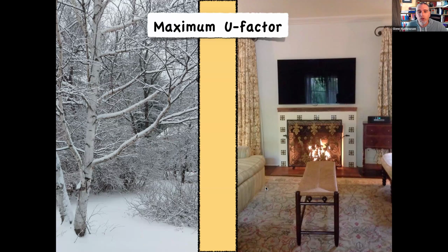With the U factor method, you calculate and determine the performance of your assembly by specifically what you built. So it's going to account for the studs in here. Studs have a pretty high U factor. They're going to allow movement of heat energy faster through the studs than, say, through insulation. So whether those are metal studs or wood studs, it's going to have a different U factor. This method lets you get credit, or counts you, for exactly what you're using. Metal studs or wood studs, 24-inch on center, 12-inch on center. How is your assembly built?